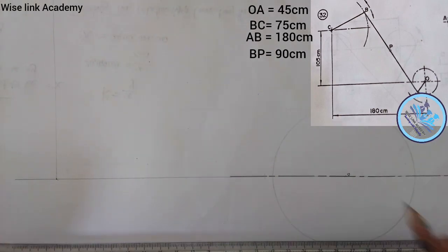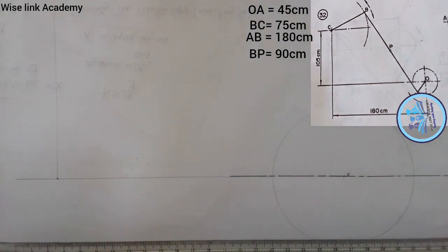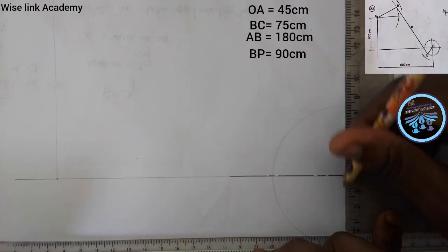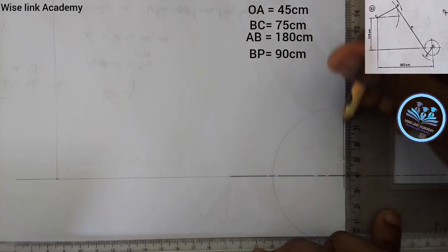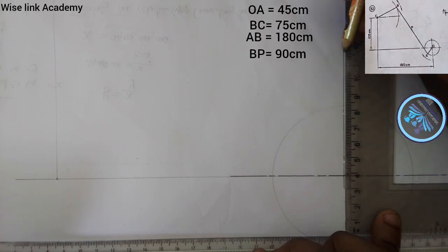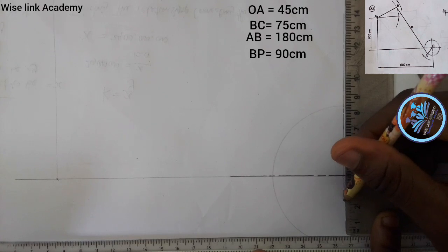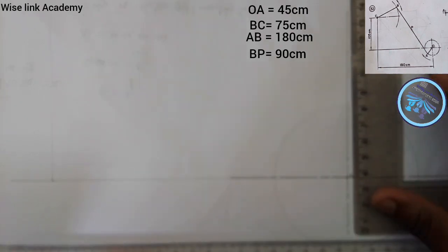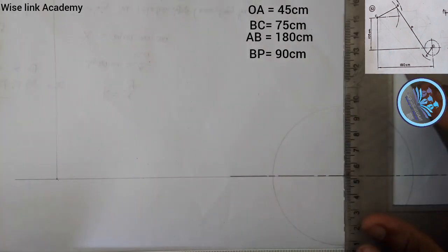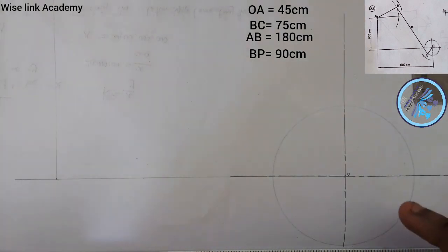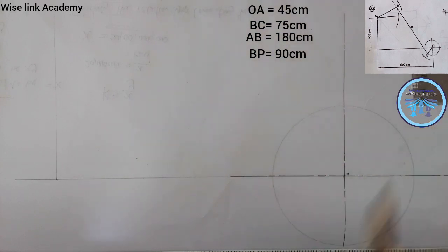As you can see, then on this center point, I'll place my T-square this way. Then I'll draw a long one, short one, long one, short one, long one, short one, long one. Similarly, you do it straight down. So you'll be having this. It simply means you have produced a reasonable center point.